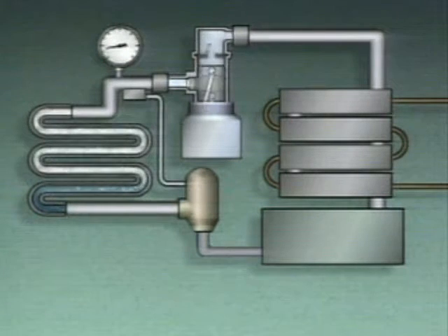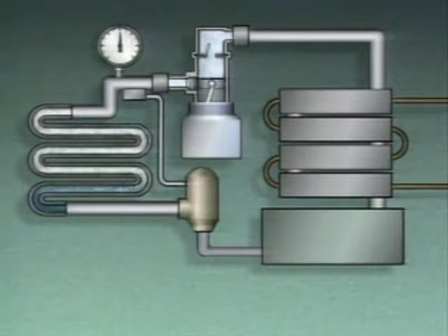and the control system may shut down the compressor. When the compressor stops, the refrigerant begins to warm up and the pressure starts to rise, so the compressor quickly restarts. Then the pressure is reduced again and the compressor again shuts off. This on and off cycling, or short cycling, will continue as long as there is a low flow condition.